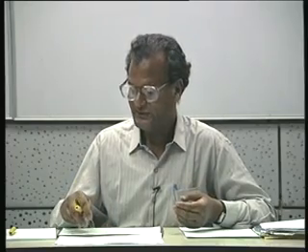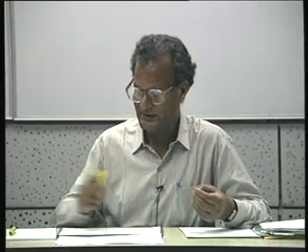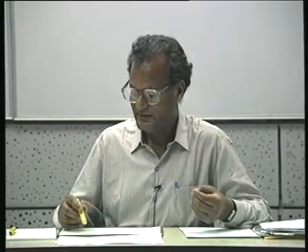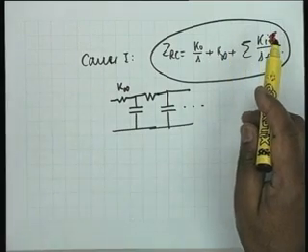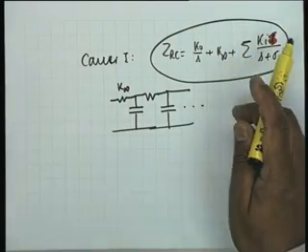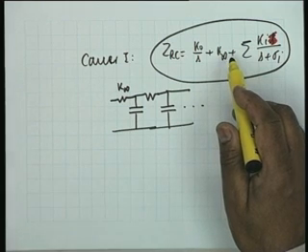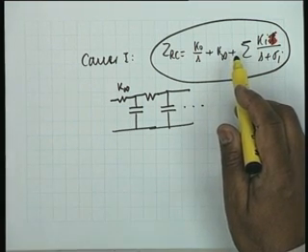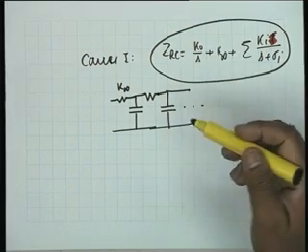Now, the starting point is important. Do you start from RC impedance or RC admittance? You see, if you remove the infinite frequency value of RC admittance, then you have made a great mistake, because you cannot remove that. From RC admittance, what you can remove is YRC of 0, not the infinite frequency value. So, one must remember that if you want to develop in Cauer 1, two things are permitted: either the infinite frequency constant value from ZRC, or a pole from YRC.